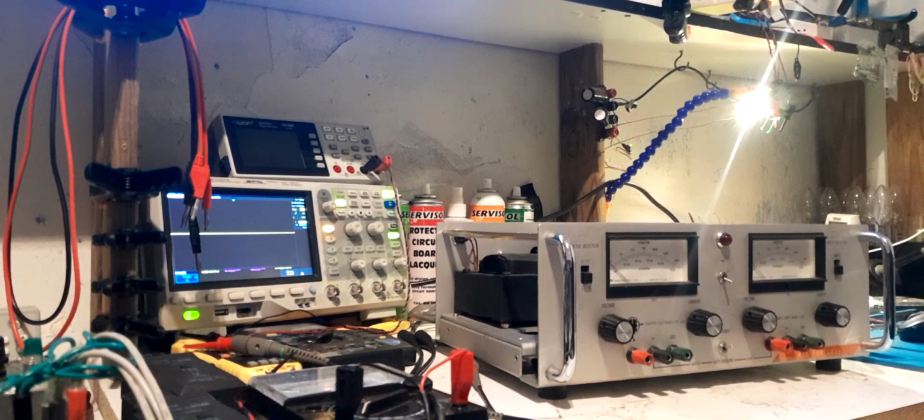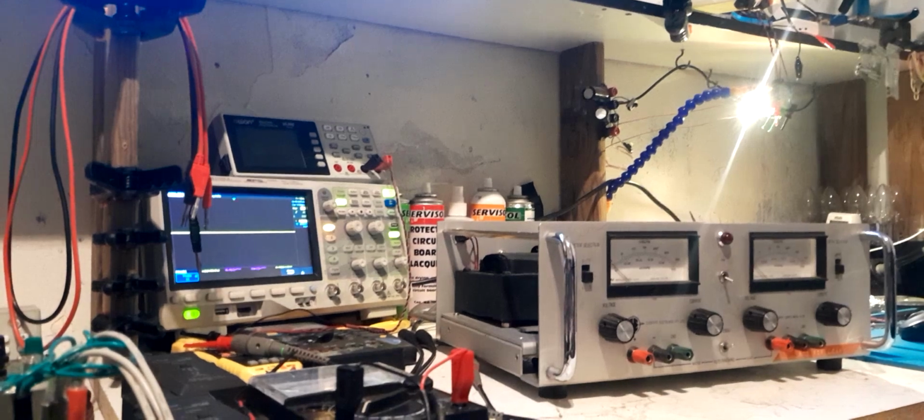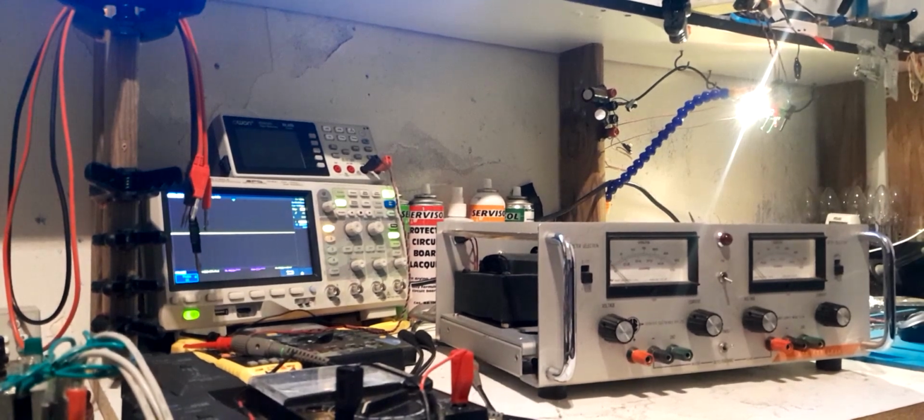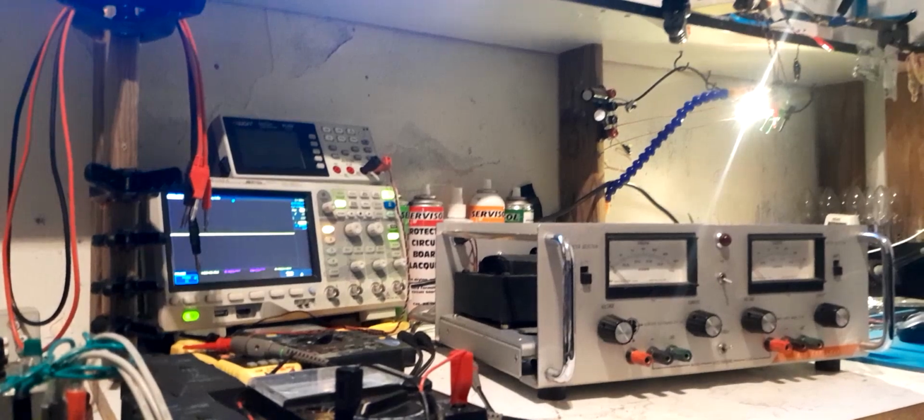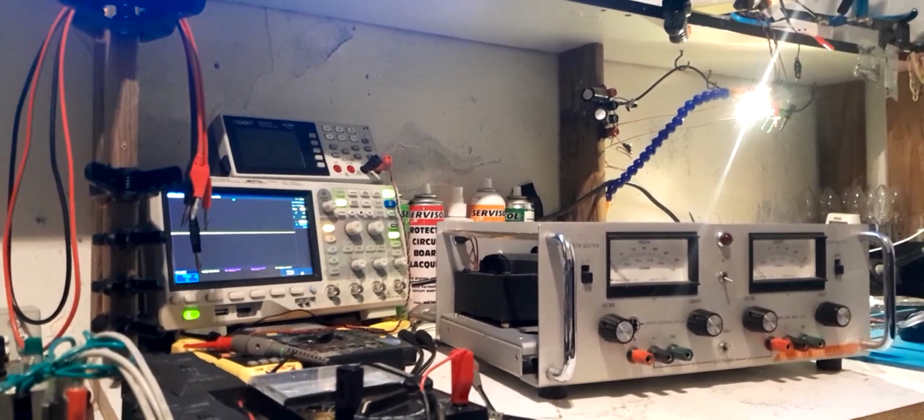Also, there's a few little tricks if you've designed switching power supplies. In most of my switching designs, I use the ATL431Bs, because I just like the 0.5% tolerance and the smaller currents required for regulation. So that's my go-to part in switch mode supplies that have a TL431 in the design, or even an LM335 or something.